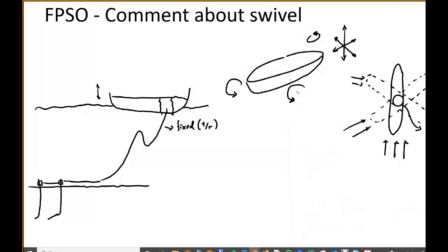So that's the part, this swivel that we have here, and we are going to see very quickly how it looks. It is what is going to be more toward the seabed, and it is going to have less movement. At least it's going to have maybe movement up and down, and some lateral movement, but it's not going to have to rotate, which is something we have to do continuously in an FPSO to take into account weather changes. So that allows that accommodation.